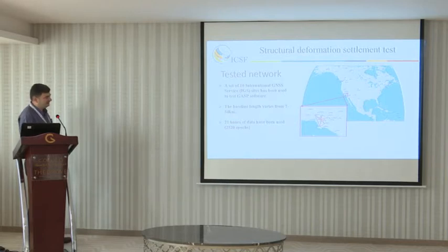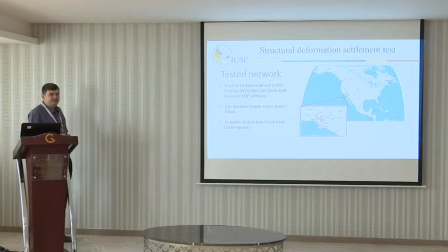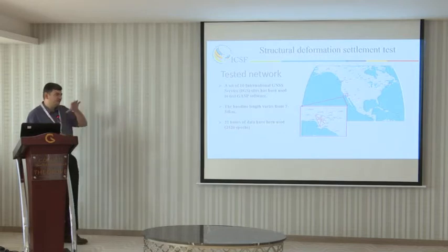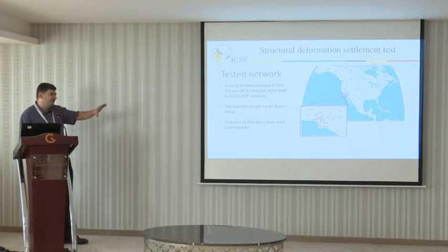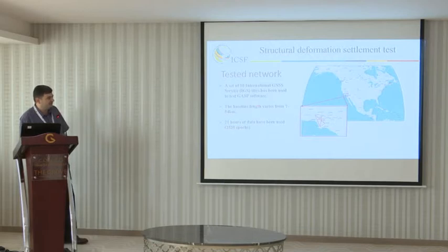Now, about baselines: in the GPS world, we always use two stations. We put one on a known point and one on an unknown point. The one on the known point, we call the base, and the other one, we call the rover. The line between the two receivers we call the baseline, and the distance between them is obviously the baseline length. For our experiment here, the baseline length was from 7 to 54 kilometers.